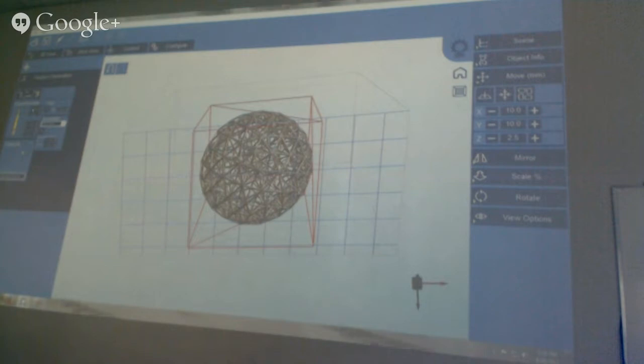And we would like to have a smaller tip, so after you cut it, it won't give you a large scar. So 0.1 is too little, it's not reliable? You increase from 0.1 to 0.3, so 0.1 is not reliable? No, it won't work, because it's so tiny that when you level it, it's going to break. And this is a smaller object. If you print something big, you probably have to increase to 0.4, 0.5. This is the radius, so times 2 gets the diameter.